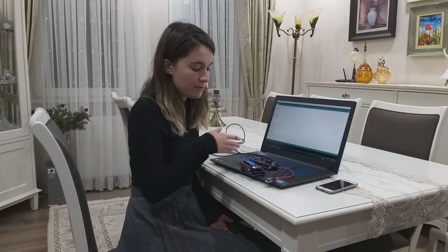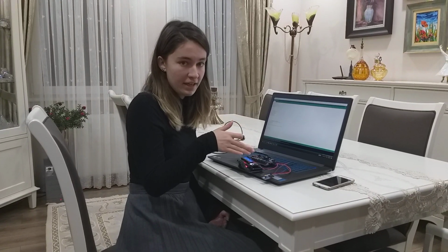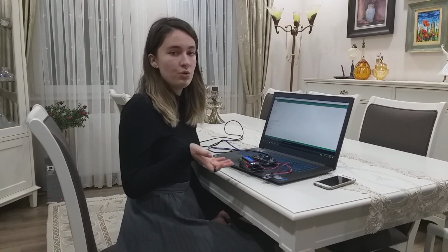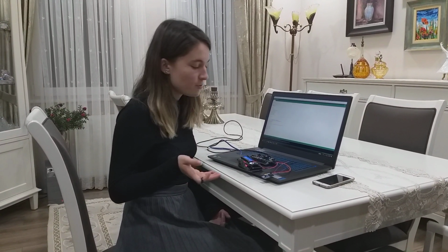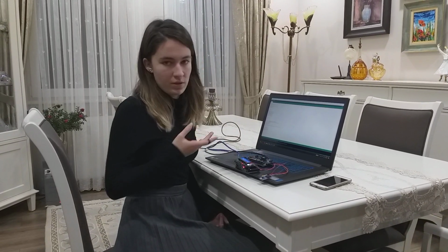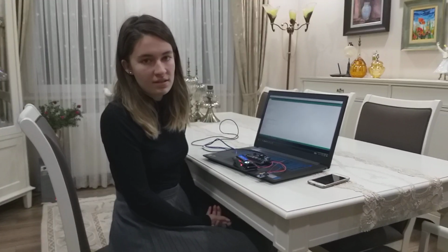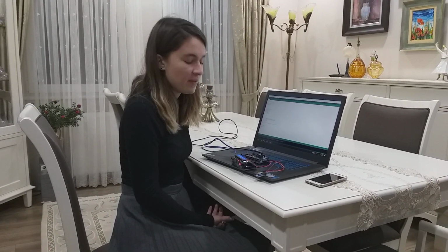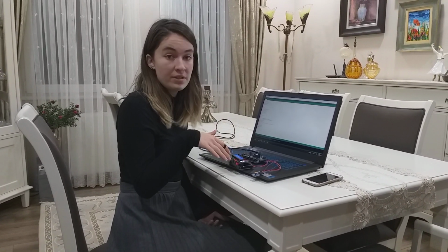It chooses the device with which the master will communicate, and it is also useful for situations when there is more than one slave, but in this one, since it has one slave, it is directly connected to it. The other port is the most important one. It is the serial clock port, and it creates the clock signal between the 2 devices. By doing this, it syncs the 2 devices so that a healthy communication between them occurs. In SPI communication, the device that creates this clock signal is called the master, and the one that receives it is called the slave.